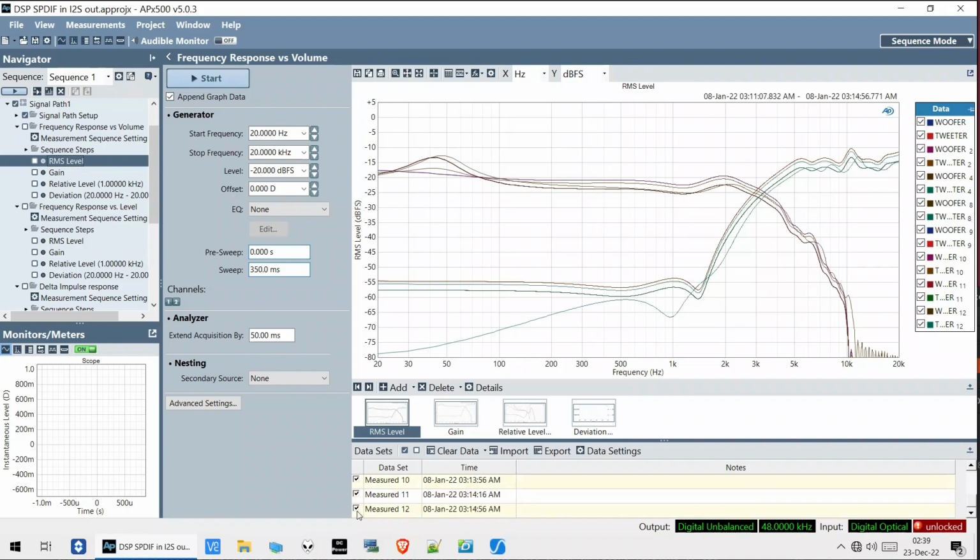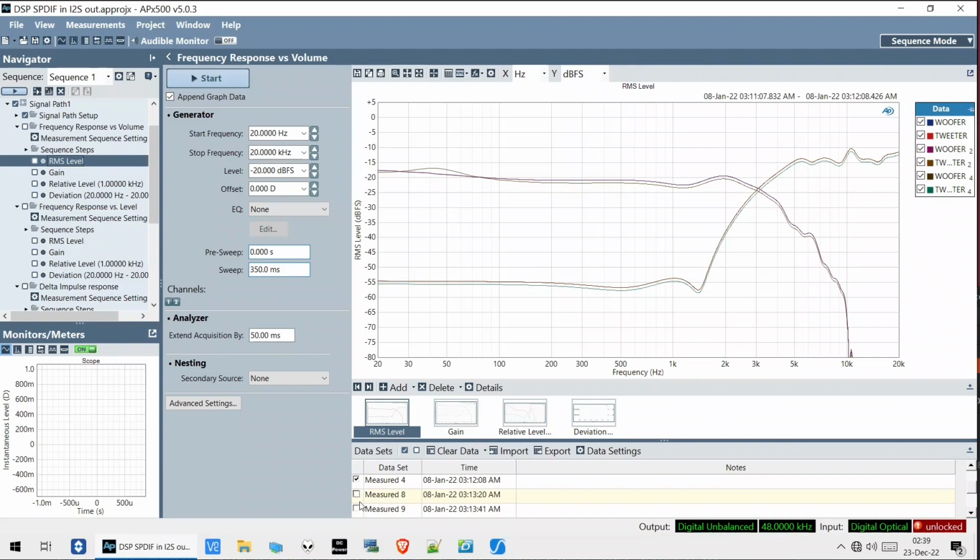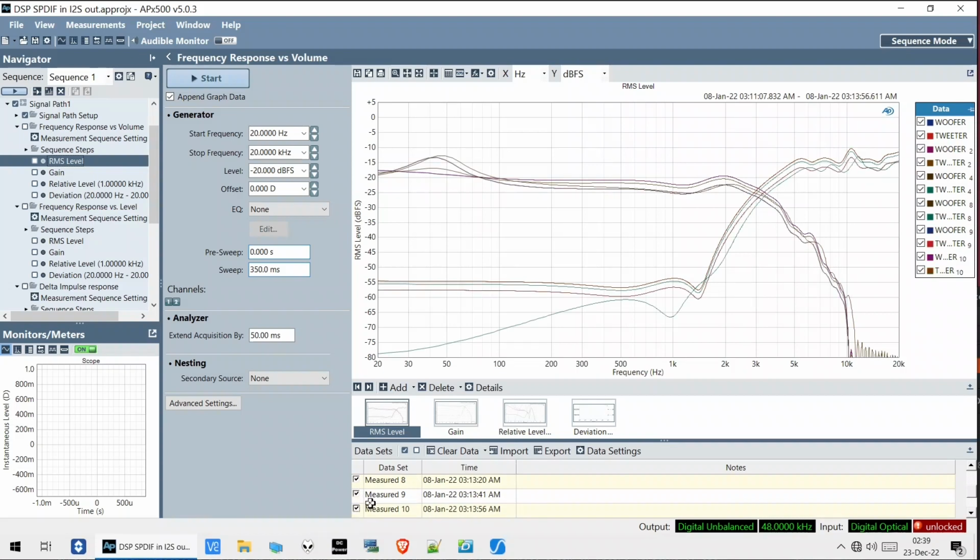We'll see, if we remove some of the lower volumes, that as the level goes up, the amount of bass boost is going down until there is essentially no bass boost left. So this has nothing to do with our distortion problem. This is just characterizing what the DSP does and trying to see if the effect that was described in the AES paper is actually present. So this is actually a pretty clever idea. You get more bass boost for a given excursion, so this is all positive.